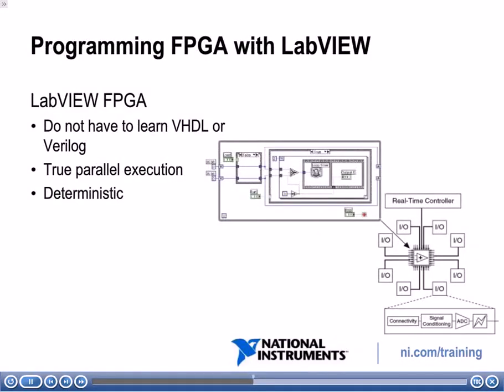Let's take a look at some of the benefits of using LabVIEW FPGA. If you know how to use LabVIEW and also learn a couple of the things specific to programming LabVIEW FPGA that we talk about in this course, you don't have to learn VHDL or Verilog. You can simply use LabVIEW to program the functionality of your FPGA. And if you have something on an FPGA, then you're going to have true parallel execution, and we'll talk about that a little more in the next slide. Also, because the FPGA is implemented in hardware, it's going to be very reliable and very deterministic.